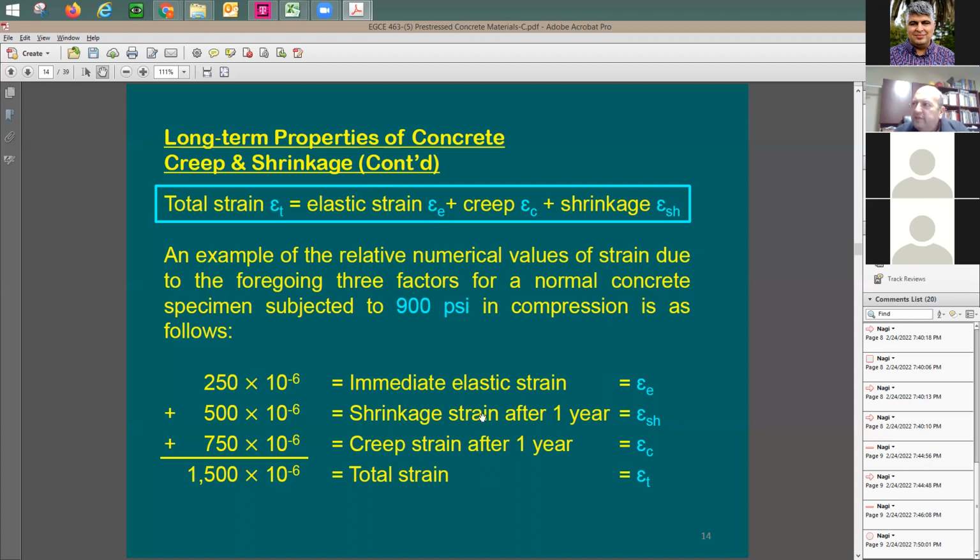So which one here is the most critical one? I'm gonna say the creep. How would you control it? I'm gonna say the aggregate and the amount of reinforcement that you put in there. This is in general terms, right? How about the shrinkage? Yeah, shrinkage is gonna be very important. Look at the two values, 1250 for both of them versus the immediate elastic strain.